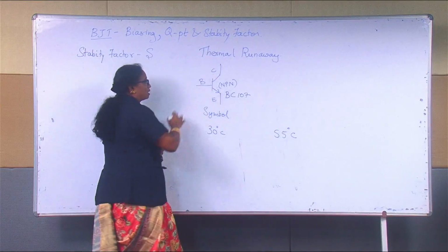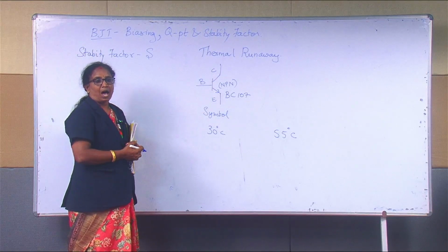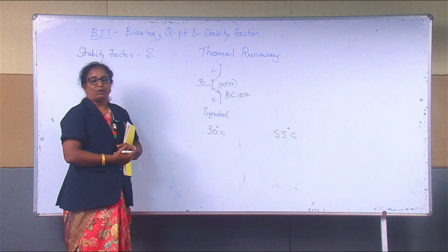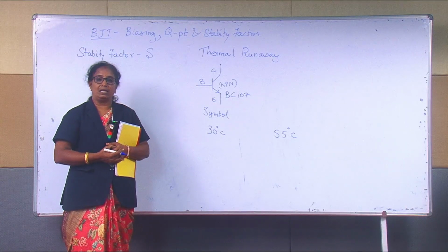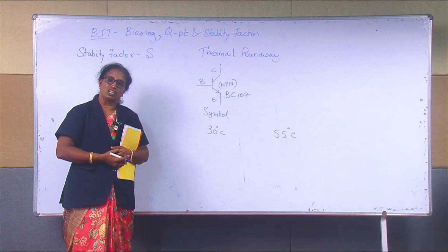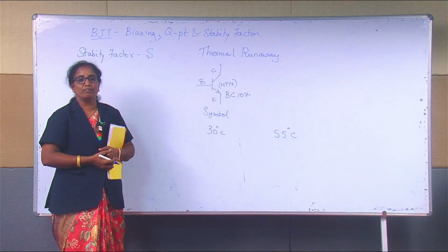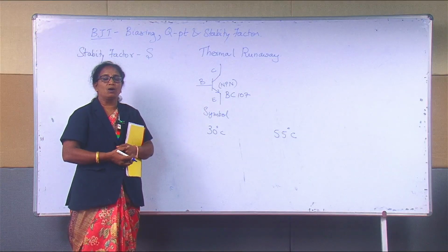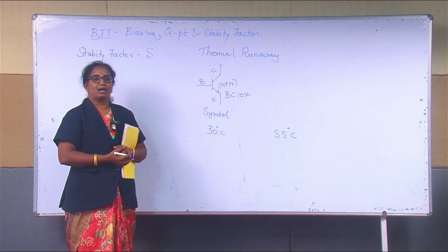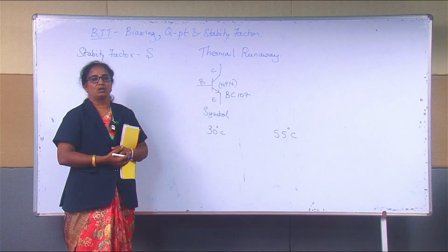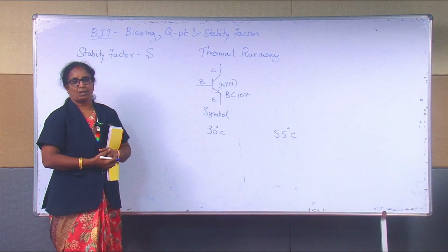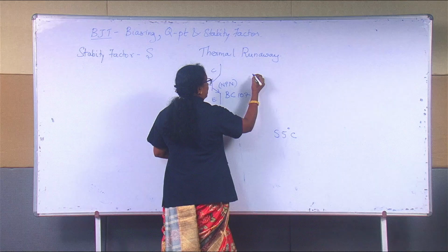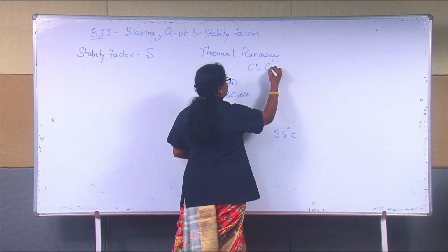So thermal runaway is, as the operating temperature is increased, we will have a very large increase in the movement of charge carriers, contributing a large value of collector current, which may exceed the safe operating collector current or operating conditions of the device, that may lead to the breakage or burnout of the device.